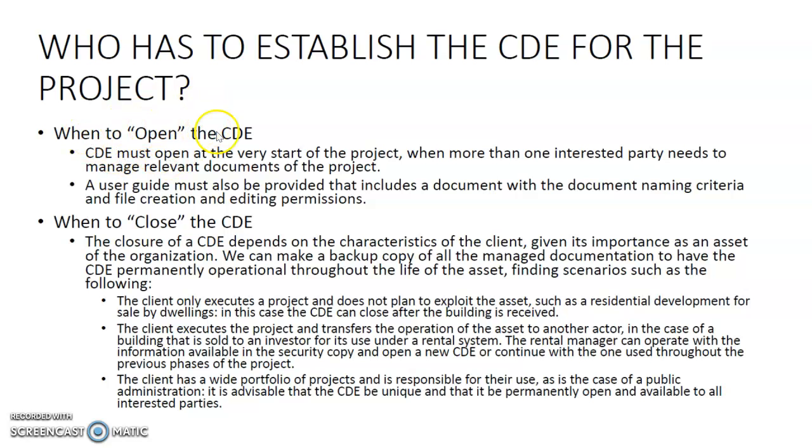So when do we open or create the CDE? The CDE must open at the very beginning or very start of the project, when more than one interested party needs to manage relevant documents of the project. A user guide must also be provided that includes a document with document naming criteria and file creation and editing permission. When do we close the CDE?